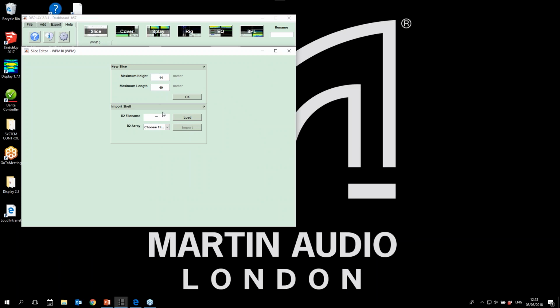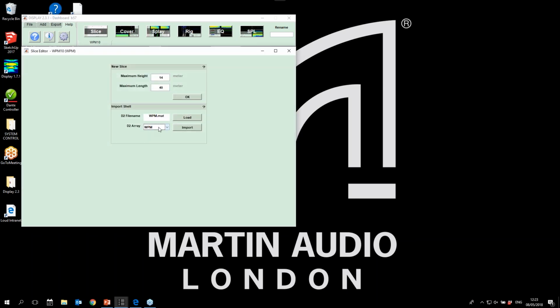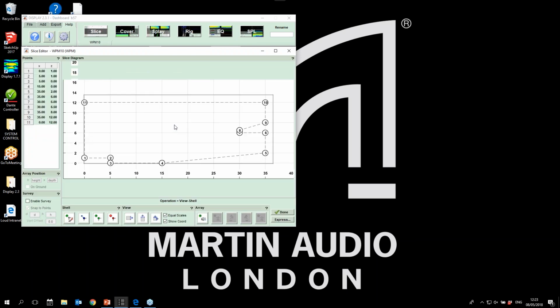So what I'm going to do, I've already created the shell, so I'm going to load that in. To do that, we click load, open up a file, and we see here we have an array, and then we import. So this shell is the base of the venue we're just working from. And we can see that we have from points 1 to 11 working in an anti-clockwise fashion all the way around, and they are displayed here. We can edit these just by clicking and changing measures and just tabbing through if we want to. We can add a point just by dropping it in, and we can remove a point just by hitting the red button and taking it back out.